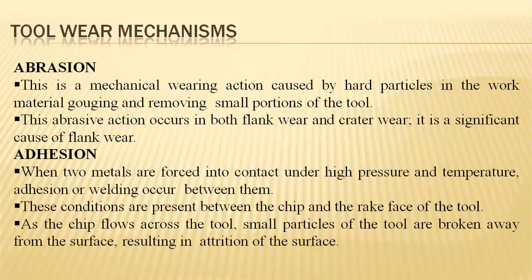So the majority of the material will be removed from the work part, but a minute portion, about 1/100th of the material, leads to work conditions on the surface of the tool that result in the attrition of the surface.